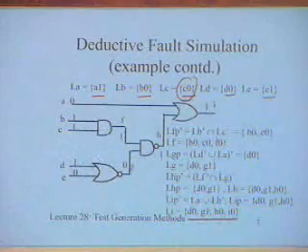So when I did fault simulation, or when I did deductive fault simulation, in both cases please remember one thing: I worked at the gate level. Typically most fault simulators work at gate level, but increasingly, because circuit complexity is increasing, people are also looking at doing these simulations at higher levels. There is really no problem in doing simulations at higher levels, because what you really need to do, in the parallel fault simulation case, is essentially write the function.